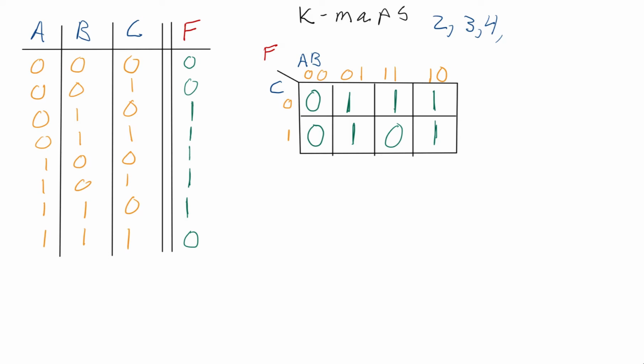They have to be in groups of either 1, 2, or 4, or 6. And you cannot circle diagonally. You can just circle horizontally or vertically. And I did say a group of 6. That's incorrect. You can only make circles the size of 2, 4, 8, and maybe 16. And if you notice, these are powers of 2. So the number of ones that you put inside of your circle can either be 2, 4, 8, or 16.